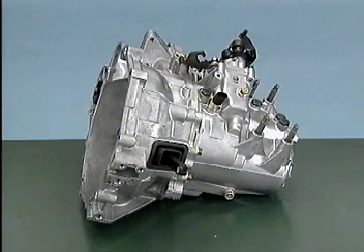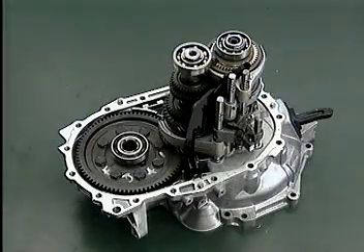Two new 5-speed manual transaxles are used on the Mirage for 1997. The F5M41 is used with the 1.5 liter engine, and the F5M42 is used with the 1.8 liter engine. Because of the new east-to-west mounting, both transaxles use a 2-shaft design instead of a 3-shaft design. The intermediate shaft and its components have been eliminated. This aids in weight reduction and noise suppression.